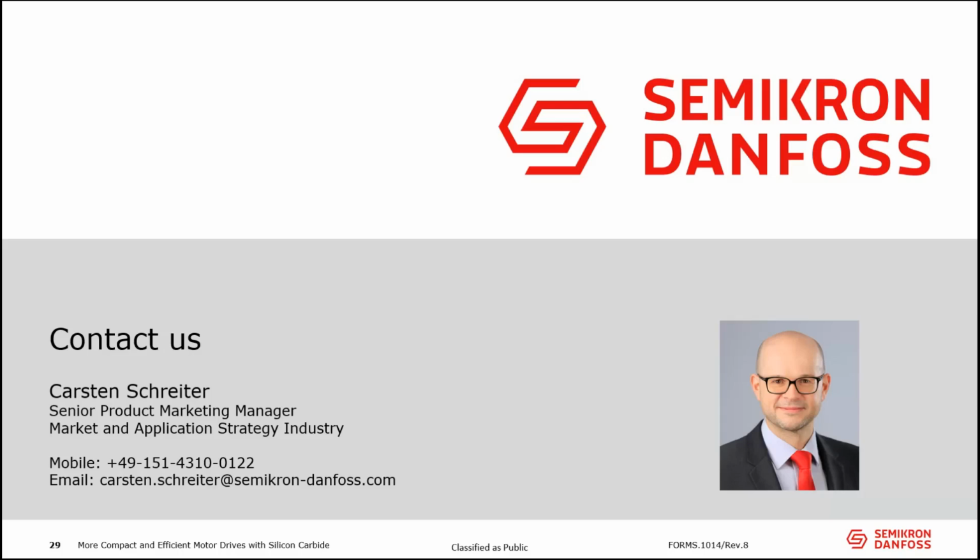Okay, but we do also have those modules you mentioned that have IGBTs plus silicon carbide Schottky barrier diodes as the freewheeling diodes, right? I can almost say we had them, because it turned out that they are not a cost competitive solution. Having the full SiC module nowadays is more cost competitive than putting an IGBT and a silicon carbide Schottky barrier diode next to it, with all the bondings and the soldering and whatever you need there. I would never go for anything else than full SiC nowadays.